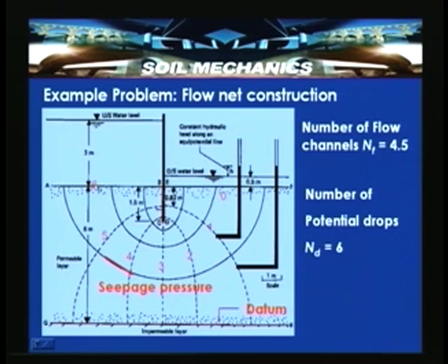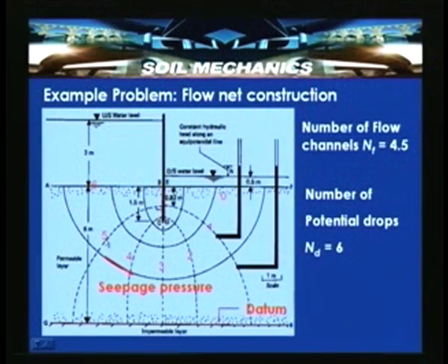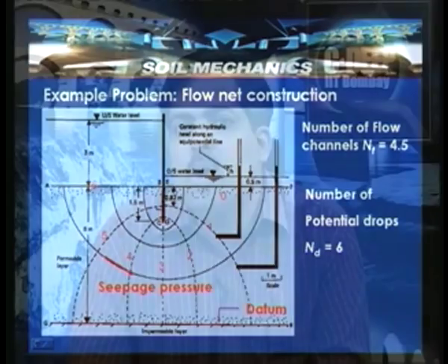And here the total head which is available, that is 2.5 meter, is available for the flow to take place. So, if you look into it here, at this particular point, 6 by 6 into the total head, that is 2.5 meter head, is there. So, here 5 by 6 into 2.5 meter is there. That means the drop which has occurred when the flow takes place from 0.6 to 0.5 is nothing but 6 by 6 into 2.5 minus 5 by 6 into 2.5. So, that is the drop which is taking place.